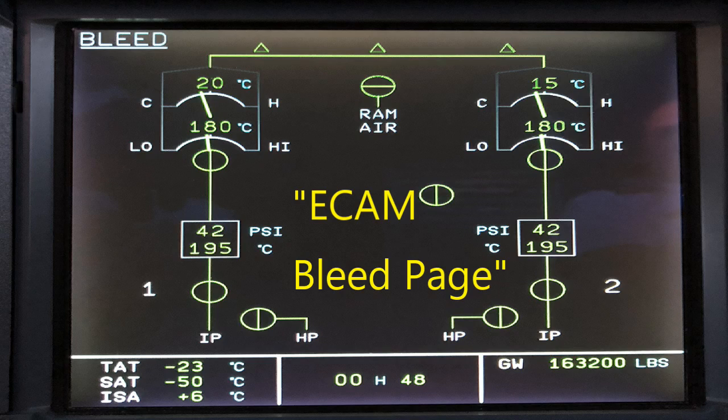So what else do the BMCs control? What else are they monitoring? We have a bleed leak detection system, and this is going to be detecting not just leaks but also bursts that might occur. A leak is dangerous, and a burst is definitely dangerous, causing damage to other components. You don't want a continual flow of air going in through those ducts.